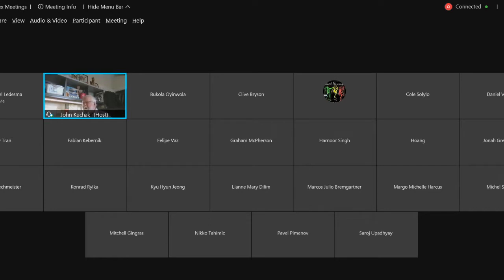It gives you a background to the point that when we do mixed designs, you'll understand how specific gravity, the aggregates, are going to be used to determine volumes. When we get into mixed designs, there's different ways of doing it, okay? You can actually do it from previous test data, run a statistical analysis on it, and if previous test data for that mixed design that you want to use is good, you can go ahead and use it. The most common one is the absolute volume, and that's the one we're going to be working with.